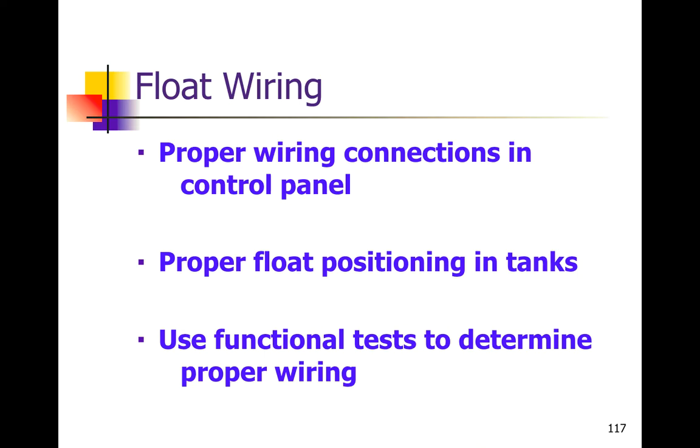So the first thing we want to do, again, proper wiring connections inside the control panel. Then we're also going to look at the proper float positioning in the tank itself. And then to make sure that the wires connected to the control panel are correct, we're going to do functional tests.